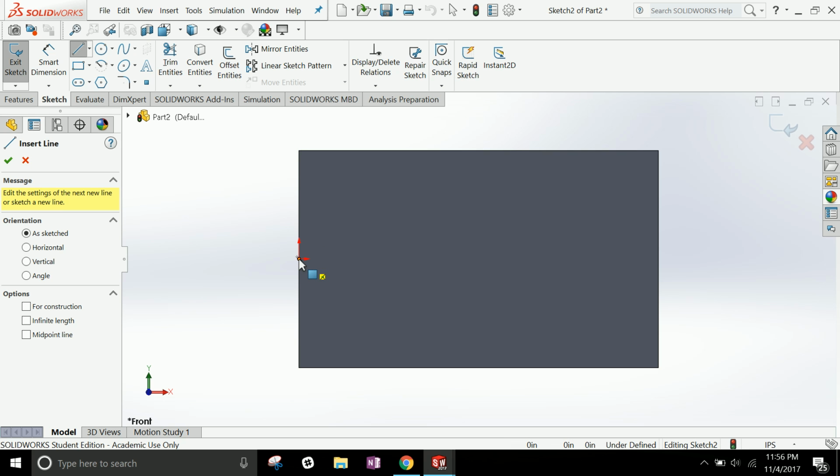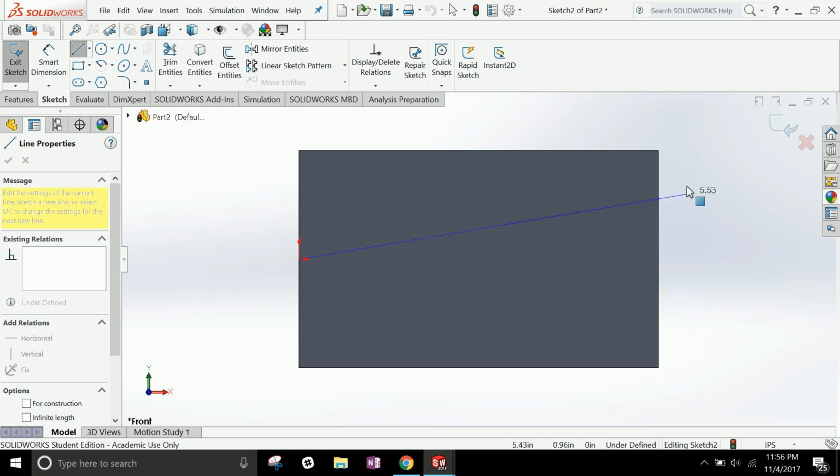It's going to give me these nice relations. So if I click and start dragging out, it's also going to snap and tell me, oh, there you go, you're 180 degrees. Oh, there you go, you're 0 degrees, 90 degrees, and like so. So that's going to be very helpful. It's also going to give you the 45s, and it's going to help you once you've already created some. So what I'm going to do is try to make 2 steps. So I'm going to drag it right to the middle, make sure it's at 180, and click. Now I'm going to go up, and click again.